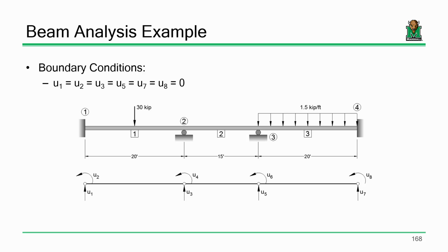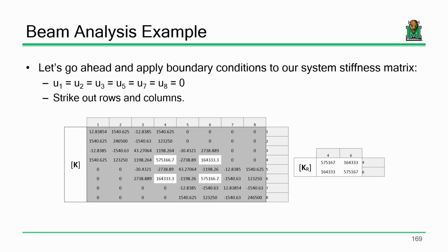Another point we made last time is that for elements like a beam, where all we care about is vertical translation and rotation, we really don't care about the difference between a roller and a hinge, because all we care about is whether or not the joint can translate vertically and whether or not it can rotate. That's the same behavior for a roller or a pin in this regard. That only starts to matter when we look at frame analysis.